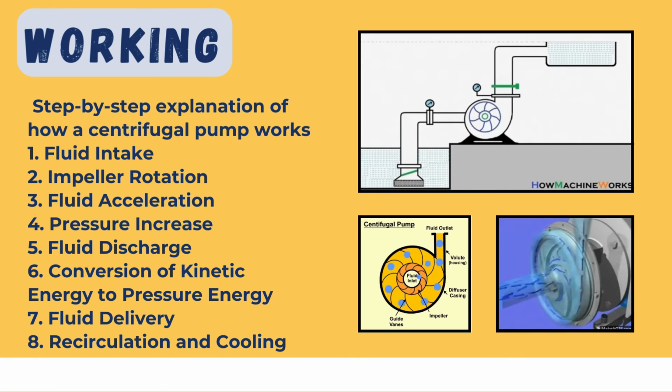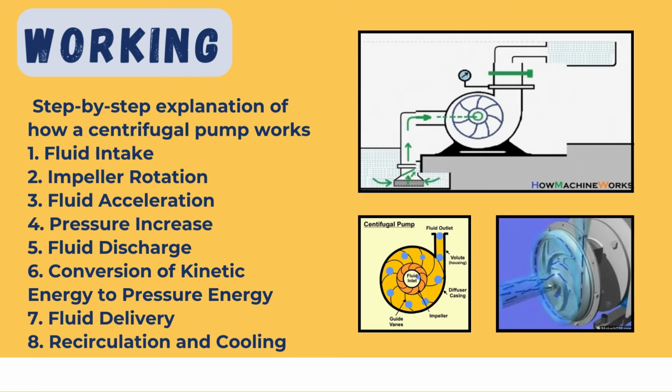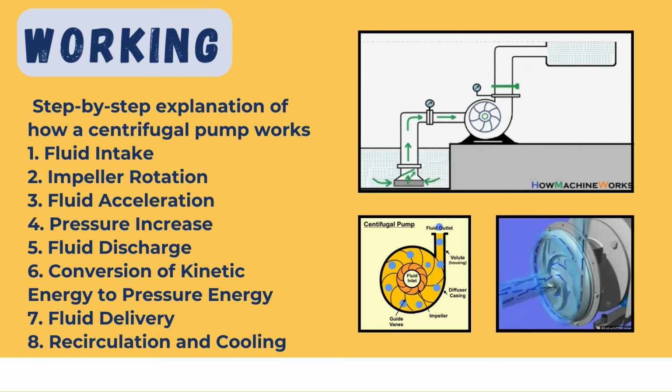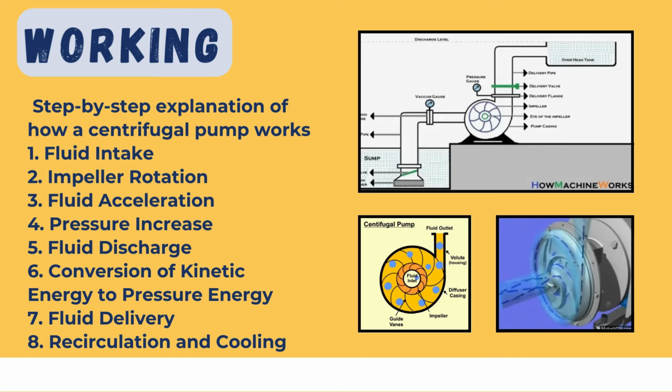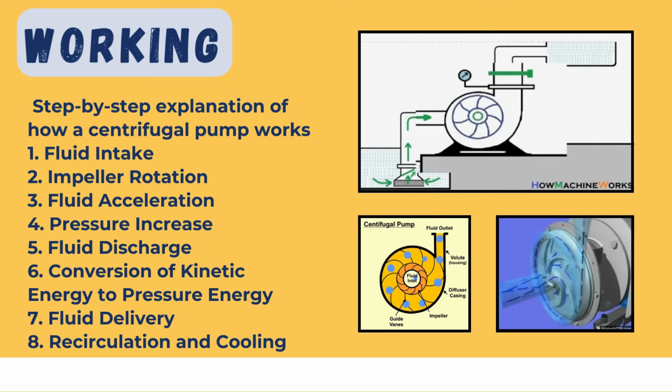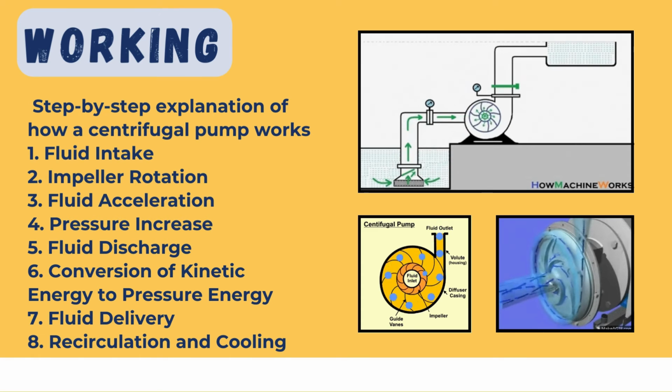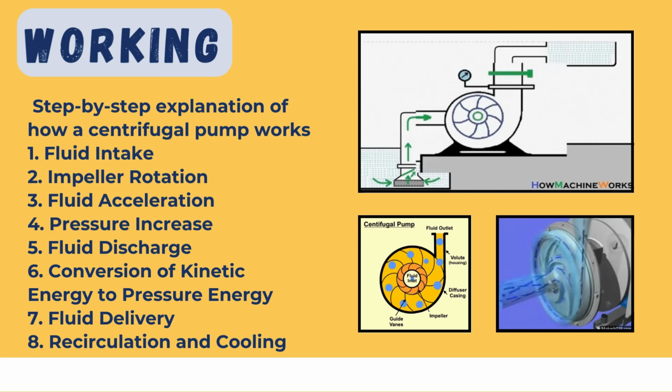Okay guys, so let's quickly recall the 3 working steps of the centrifugal pump. The first was the fluid intake, where the fluid enters the pump at the center of the impeller, after which comes the impeller rotation part. In impeller rotation, the impeller rotates, causing the fluid to flow in a radially outward direction, which is because of the centrifugal force, right? And because of the impeller rotation, the fluid acceleration takes place, right?